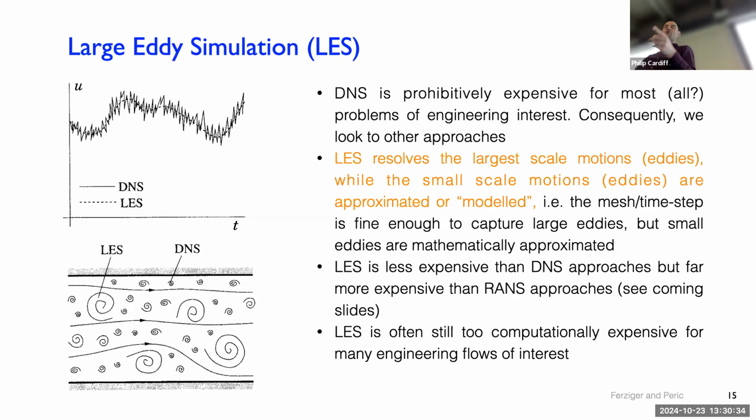When we go to the other methods, which don't describe turbulence precisely, they have to be calibrated or tuned to give reasonable results. So what do we tune them against? We can tune them against experiments, and that's what you do, but you can also tune them against DNS models. So DNS is used to design or tune what are called turbulence models. We haven't talked about turbulence models yet. They let us do calculations with turbulence in practical amounts of time.